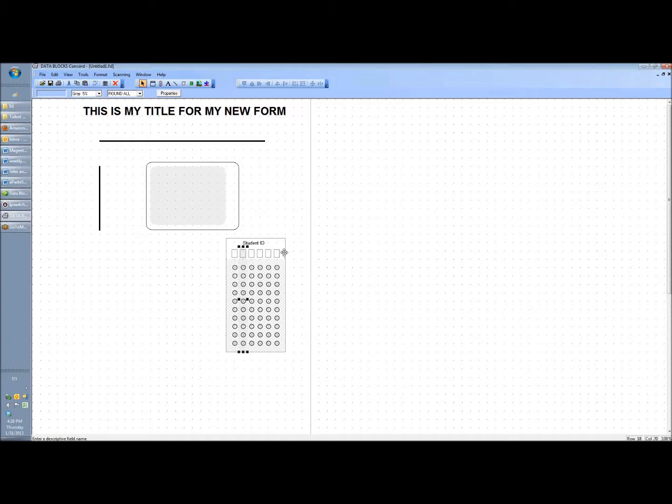We have also another very, very handy feature, and I'm going to illustrate that right now. If you have an object selected, press the Control key, move your cursor over that object, click on the left mouse button, hold it down, and drag over, and it will drag an exact copy. So we now have a second piece of shade exactly like the first one. And I'm going to do that one more time. Hold down the Control key, left click, drag, and I get an exact copy.